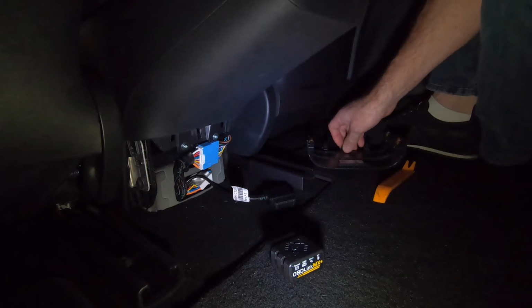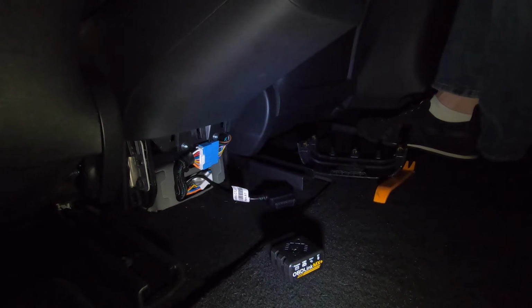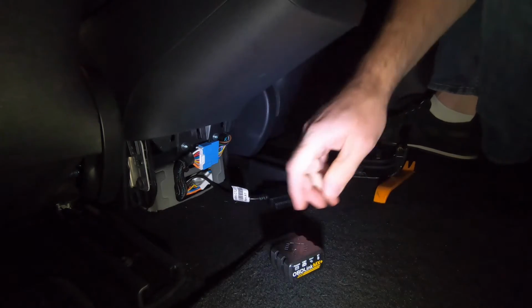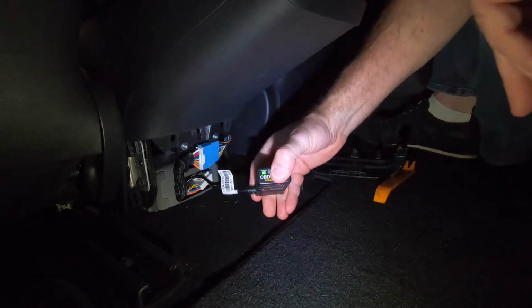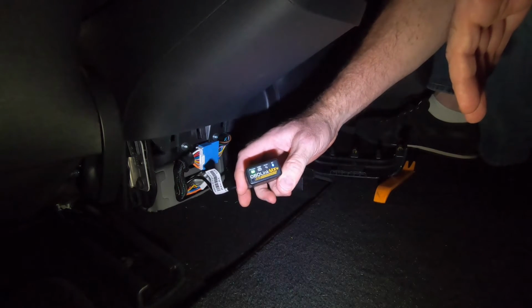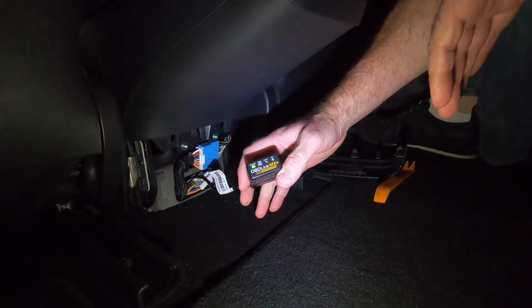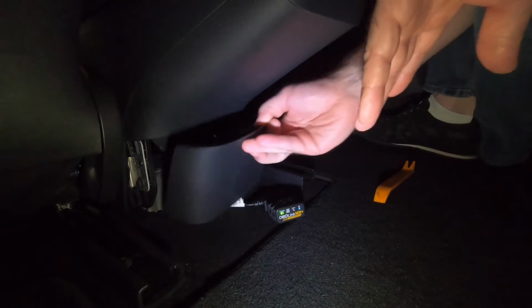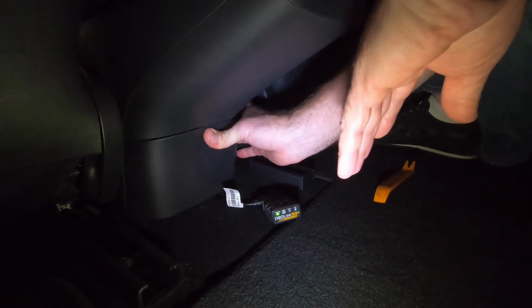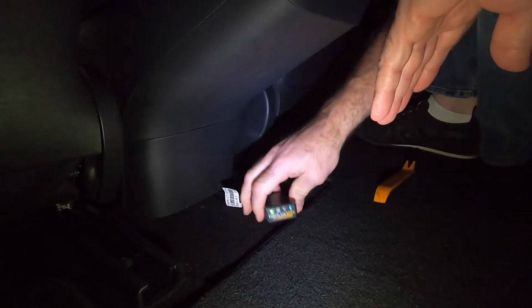Now we want to put this cover back on, but we probably need to power the car up first just to check that the power light lights up. So I'll open the door, the car's powered back up again. We'll plug the OBD adapter in. Yep, and look at that, it's powering up. No problem, we've got a nice green light there, and we've got the Bluetooth light flashing, waiting to pair with the device. We can now put the plastic cover back on. So line up that top one, clip it back in. Hear a nice snap and you can see it's all sitting flush there.